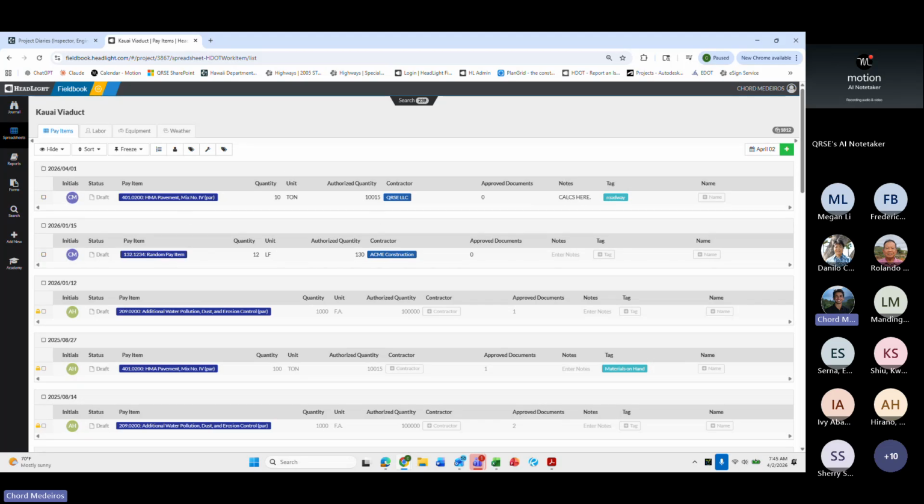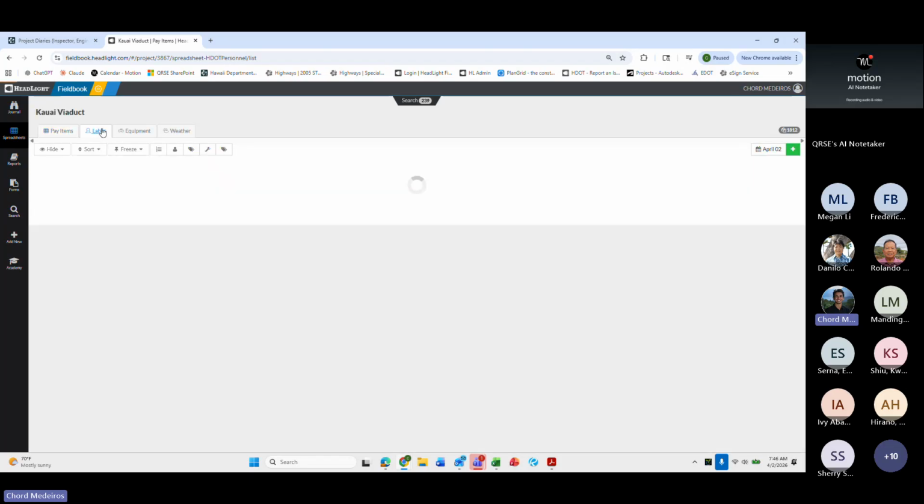And we understand that these will not always be absolutely 100% correct, that there is a little bit of room for error here, but it helps. One of the best practices I did want to highlight today is making sure that all pay items are tracked here, and also making sure that you provide any notes for the pay items, especially for lump sum, but then especially for those cubic yard and square yard unit price calculations. So I've talked enough about pay items. That was the one I wanted to highlight here today.